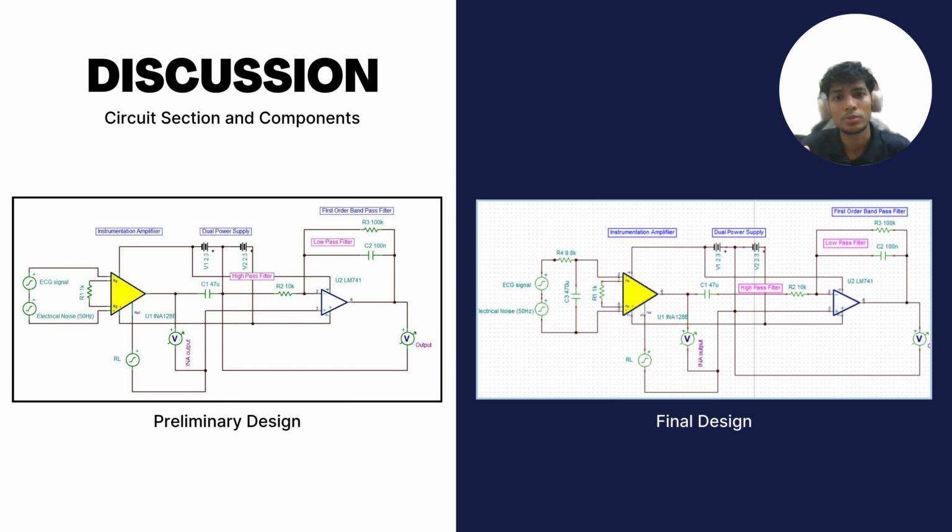Now we are moving to the circuit section and components. As you can see here, on the left side is the preliminary design and on the right side is our final design. Both circuits have four sections, which are input, amplification, filtering, and output. The INA128E instrumentation amplifier provides a gain of 51, while the filters eliminate baseline drift and high frequency noise.